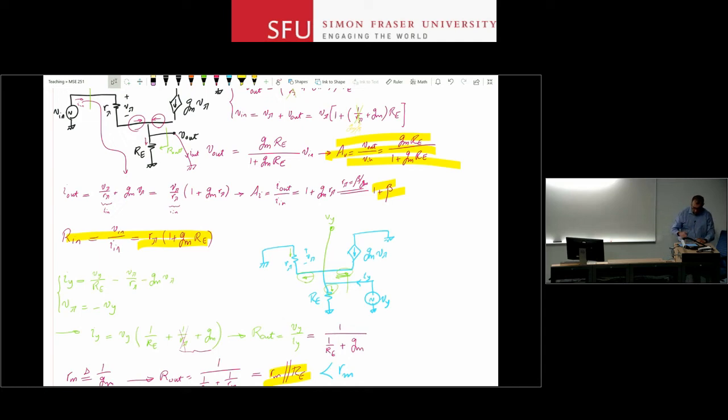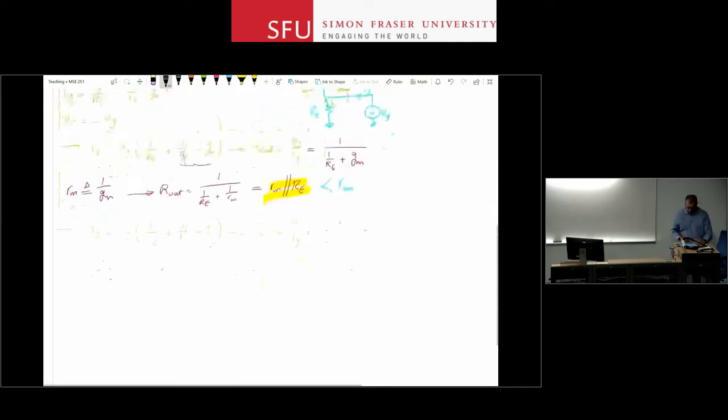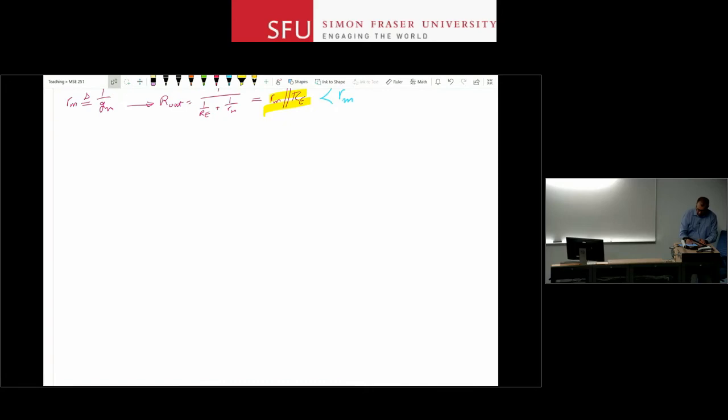Okay, and now if you look at a MOSFET equivalent for this circuit, a common drain circuit will look like this. We just drew that. I'm going to draw the small signal analysis and just write the equations for this. You are suggested to solve it. So V in and V out here. And this is VDD. Again, the device is in active region, so you go and draw the small signal equivalent circuit.